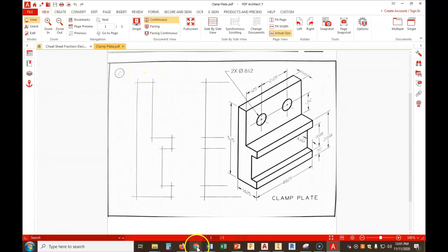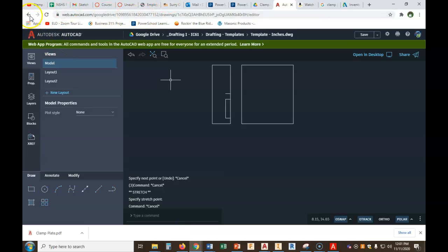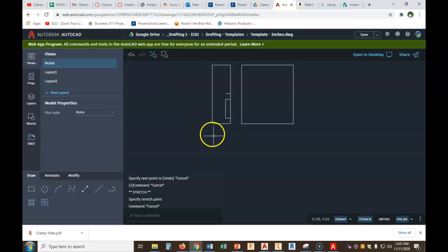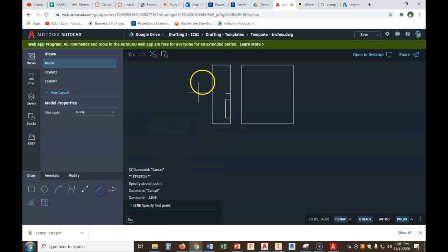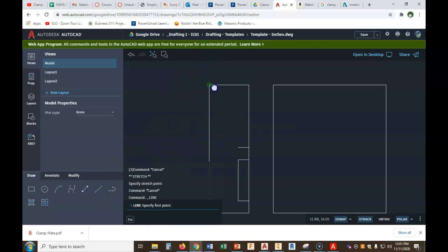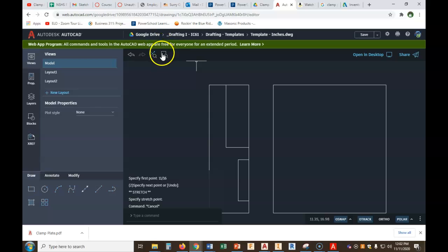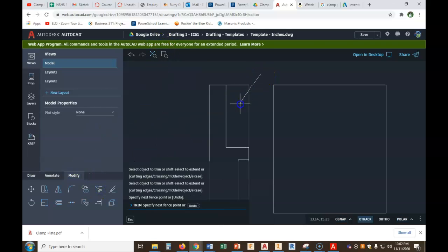Okay, so let's go do that. So a line. Uh-oh. Turn to drawing. I about messed up. Line. Hover. Let's zoom in here so we can see what we're doing. Hover, drag in, and now say 11/16. There it is. Down. How far down? Well, it ends right here at that platform. Click. There we go. Hit confirm. Now, take this and push it over to here. There we go. Now all we need to do is trim. Go into our modify, say trim. I'm going to get both of these at one time.